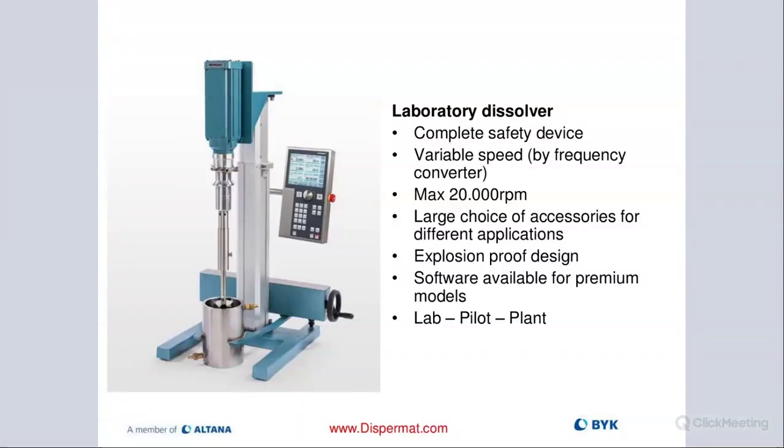So usually the H1 value never changes because containers usually have the same thickness, especially in the laboratory space. So you're probably going to be about half an inch above the bottom. So you're going to lock H1 in and it never changes. But H2 will change, and that is the upper threshold. So if I'm swapping my 1 liter container up to a 2 liter container or a 5 liter container, the height of my working area will change, right? So I need to change the H2.